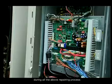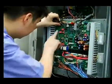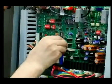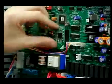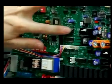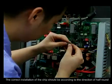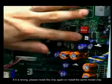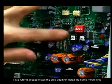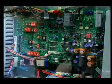During all the above repairing process, if the outdoor PC board needs to be replaced, please confirm whether the chips of the board have a malfunction. Pins of the chip may fall off, or the chips may be plugged in the reverse direction. The correct installation of the chip should be according to the direction of the half round. If it is wrong, please install the chip again or install the same model chip to the malfunction unit in order to check if the chip has a malfunction.